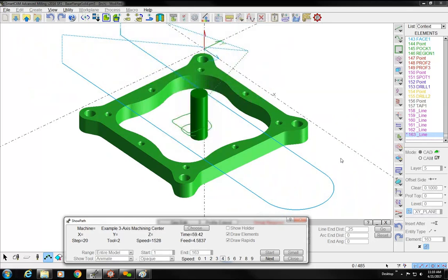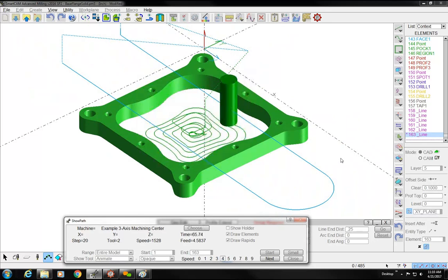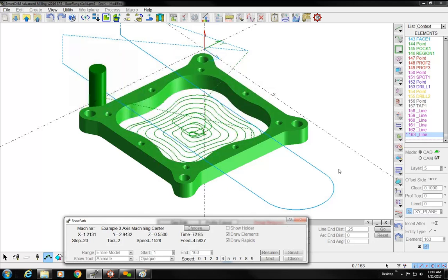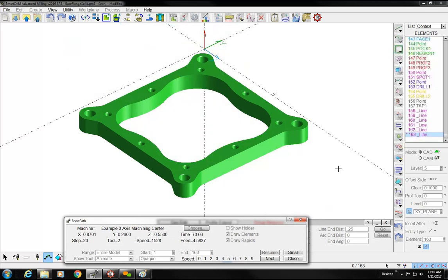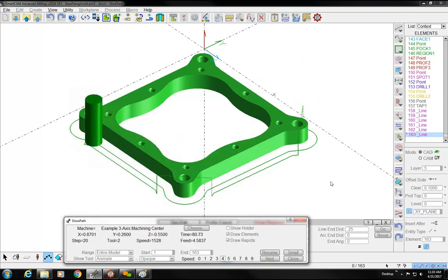At any point in here, I can hit the 0 button to stop the display, to pause, and then click on a speed and hit resume, and it'll start back up again. And hit 0 and F8 and resume, and it picks back up where it was, but the F8 erased the toolpath up to that point.